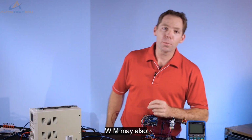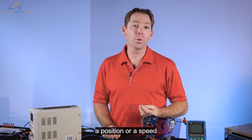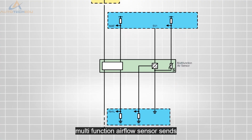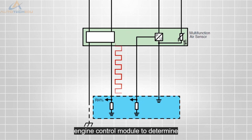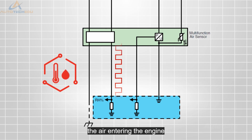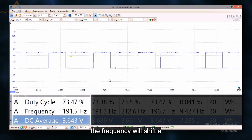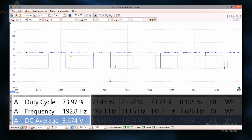PWM may also be used as an input to a control module. It can be used as a position or a speed signal, or even as a humidity sensor input. This multifunction airflow sensor sends a varying PWM and frequency signal to the engine control module to determine the temperature and humidity of the air entering the engine. By changing the temperature, the frequency will shift. A change in humidity will cause the duty cycle to change.